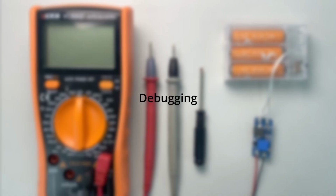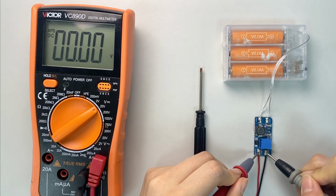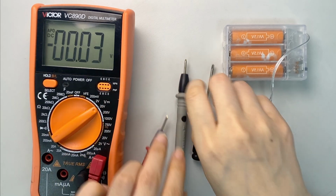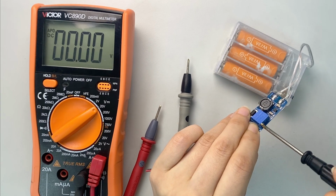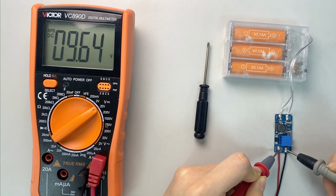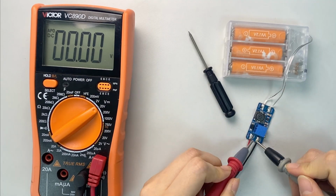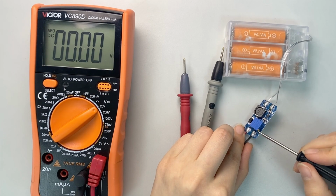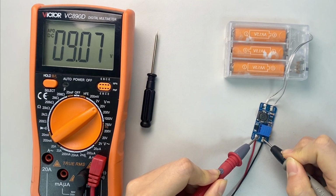After the soldering is completed, we need to debug the module to ensure it is functioning properly and outputting the required voltage. First, use a multimeter to measure the initial output voltage. Then, use a screwdriver to gently rotate the blue, adjustable resistor. Clockwise rotation decreases the voltage and counterclockwise rotation increases the voltage. Adjust the output voltage to 9 volts.